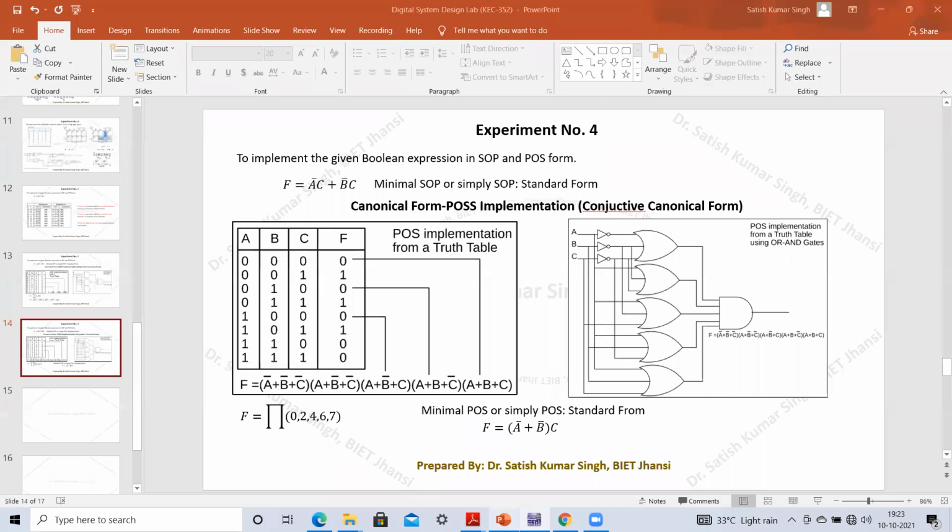Here you can see it has 3 input OR gates, because in IC form we only have 2 input OR gates. So obviously, to realize one output, we have to use 2 OR gates in the IC. Similarly, altogether, because there are a total of 5 such 3 input OR gates, I have to use a total of 10 OR gates, 5 cross 2, because for each implementation I require 2 OR gates.